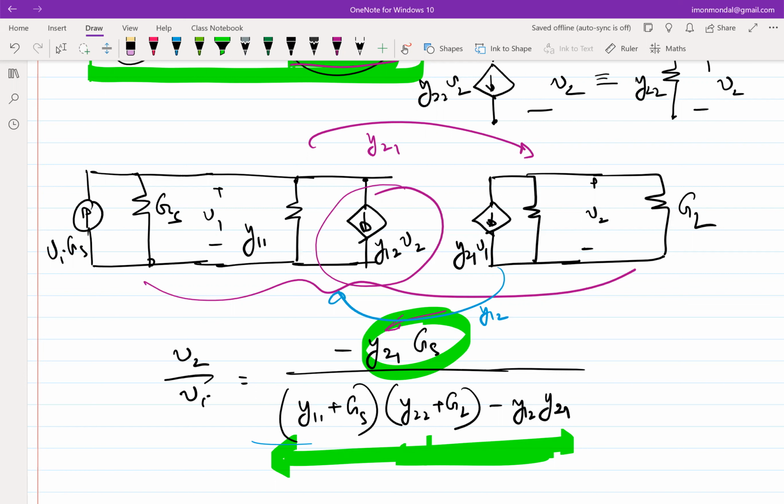Okay, I wouldn't say unwanted frequency gets introduced. For those of you who are taking E250, you will see there's a thing called the Barkhausen criterion. It is the case where, when you go around the loop, from input to output and output back to input, the overall gain is unity. Then in a negative feedback system, you can get infinite gain, and that infinite gain can happen at any particular frequency.